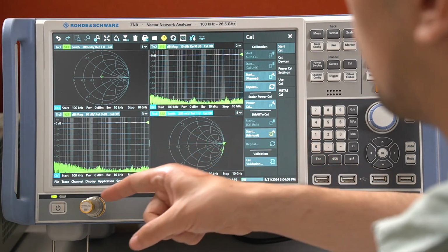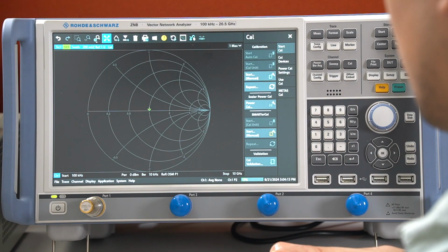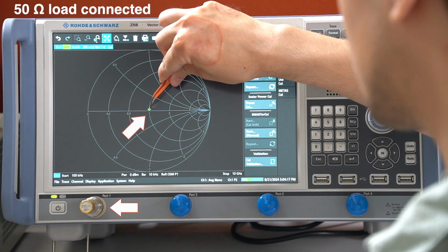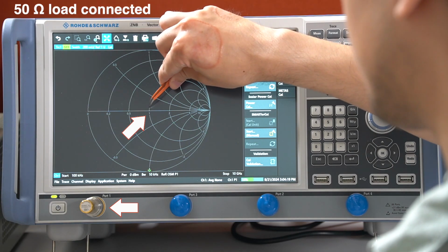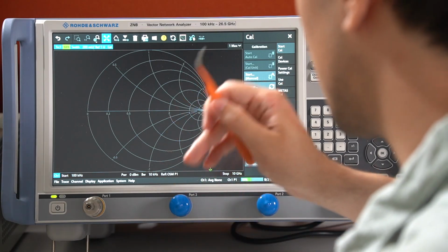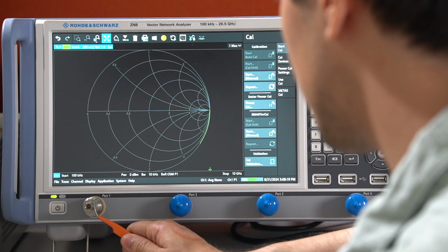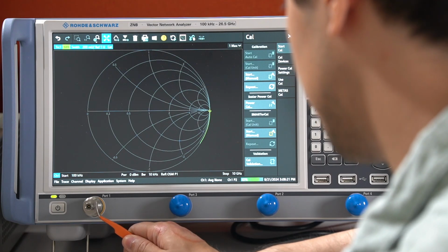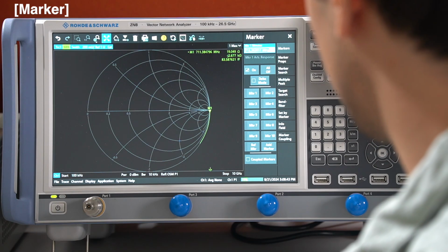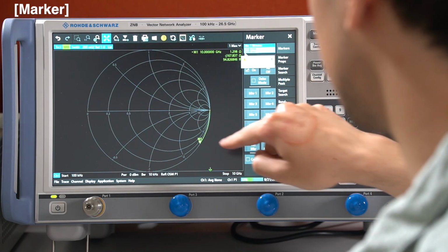And since we did the one port calibration, we are only interested in S11, and it's hard to see, but it's a very good match. So we are here directly at the matching point. And now the so-called calibration plane is exactly here where the dielectricum starts or ends. For very low frequencies, we are here at the open point, and the higher the frequency gets, at 10 GHz, we have a phase shift here.